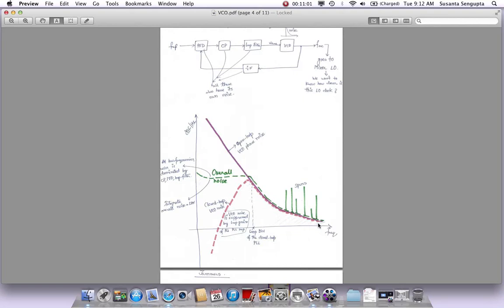And that number, this IPN, which is the integrated phase noise, you can also take and convert to jitter. There are simple formulas to do it, and you convert it back to jitter, which is a time number, a picosecond type number, which is what is used for ADC design and other kinds of design, where you want to know what is the jitter in the clock, what is the uncertainty in the clock period, or where the zero crossings are happening.